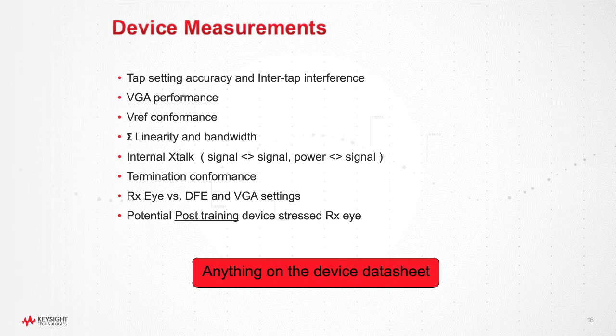You should be familiar with the VREF settings, VREF offset settings from DDR4. Clearly, if you say I want X amount of offset on the VREF, that's a signal that's buried inside the DRAM, and there needs to be a way to measure that. There are improved ways to do it over what was assumed with DDR4, which is basically looping that signal back out a data pin. But that goes beyond the scope of what we're talking about here.